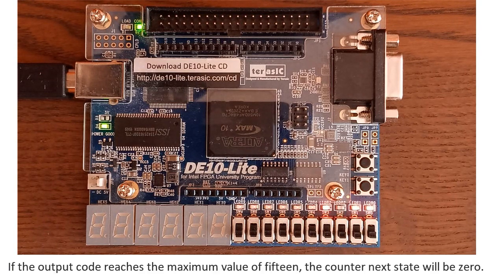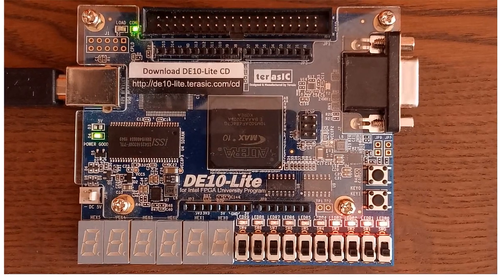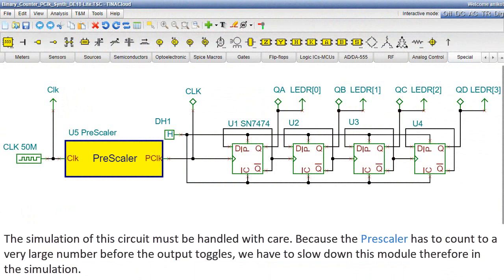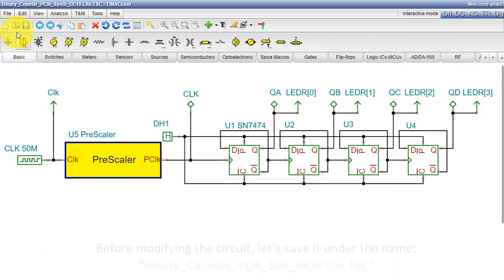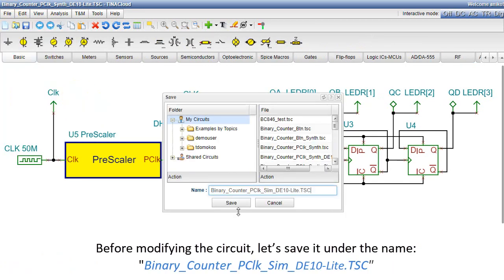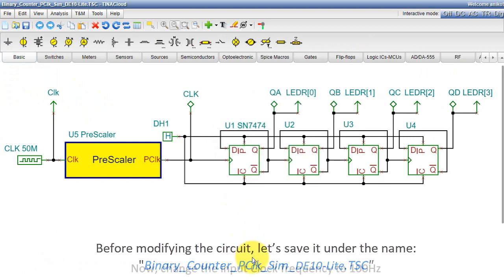If the output code reaches the maximum value of 15, the counter next state will be 0. The simulation of this circuit must be handled with care, because the prescaler has to count to a very large number before the output toggles. We have to slow down this module therefore in the simulation. Before modifying the circuit, let's save it under the name Binary Counter PCLK Sim DE10Lite.tsc.